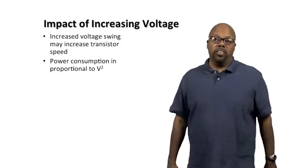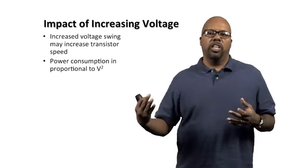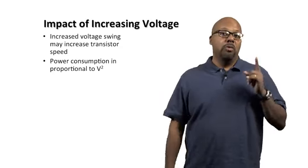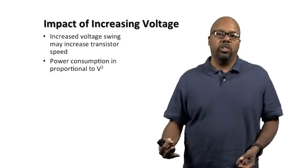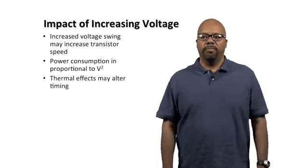But a downside of that is that power consumption increases because, well, not only does it increase from overclocking because you're doing more operations per second, but power goes with the square of voltage. So by increasing the voltage, you're significantly increasing the power consumption.